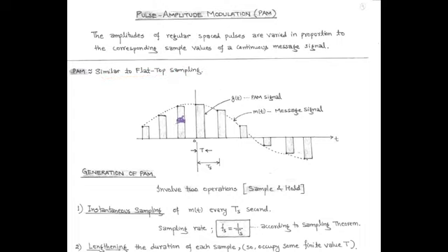In this, the top of each pulse remains flat by using a sample and hold circuit. Here, g(t) is the PAM signal corresponding to the amplitude level of the modulating signal m(t). This PAM signal has pulse width equal to capital T and sampling period Ts.